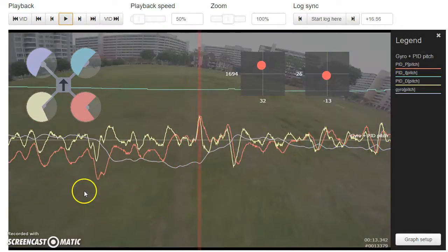So yeah, here's what I would suggest. Take your D terms down to, let's say, 15. That's certainly too low. You'll bring those back up later. But for now, take your D terms down to 15 on pitch and roll, and then start lowering your P gain a little bit at a time, maybe 0.1 at a time, maybe 0.2 at a time, just to find the area where these traces on Blackbox settle down just a little bit, especially on roll.